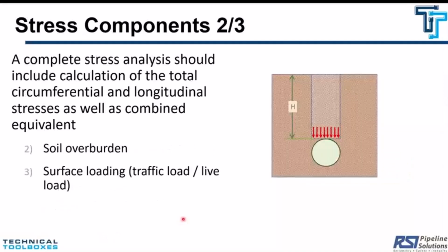All right, so what else we have? We also have existing stresses from soil overburden. And what I mean by that, again, this sketch over here shows that schematically. You have a pipe, there is an overburden, a backfill over the pipe, right? Soil backfill. That overburden applies a pressure to the pipe. So that has to be accounted for.